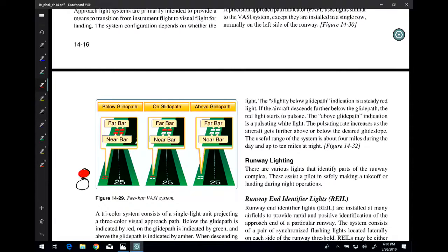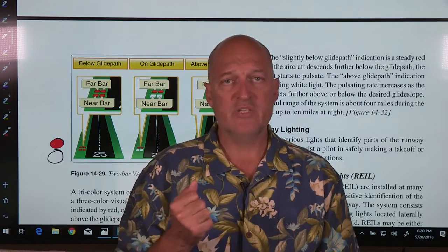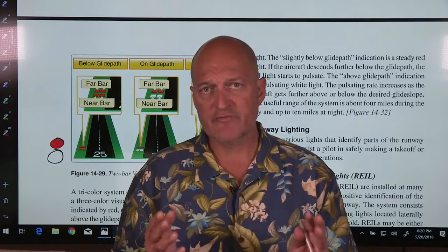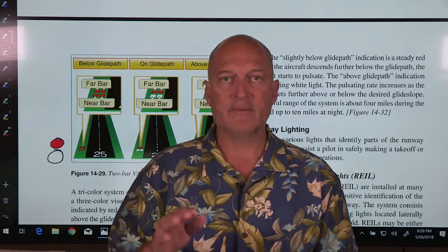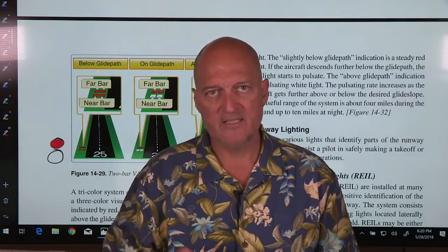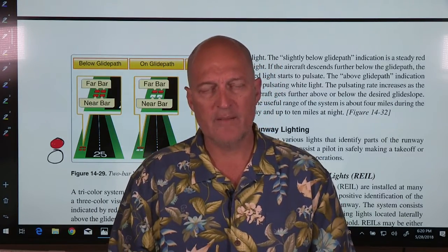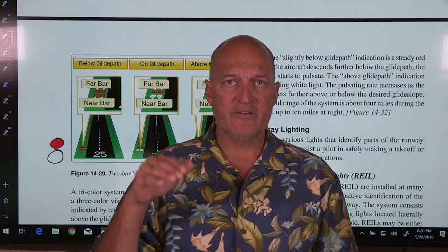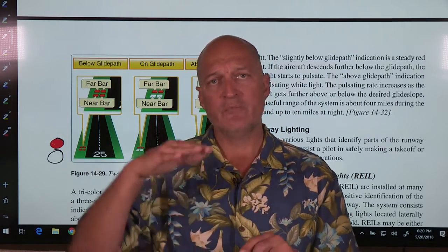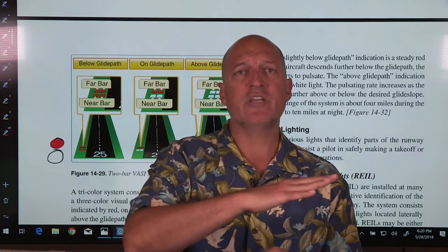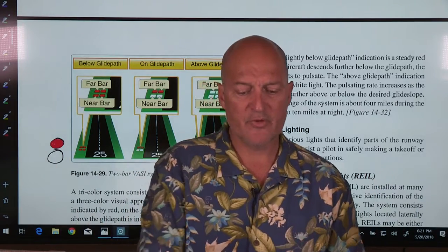I don't want to tell you that if you followed that in under a low power setting, even if you didn't pull up and start your flare, in some cases you can land the airplane. Some of the big airplanes, they set them down like that. The F-18s landing on aircraft carriers, they just kind of controlled-crash the airplane into the runway. But what you do is you follow that rate of descent in until you have the runway made, and then of course you're going to reduce power, arrest your descent, flare, touch down on the mains, let the nose come down when you can, and it's all about energy management. So that's what those are about.